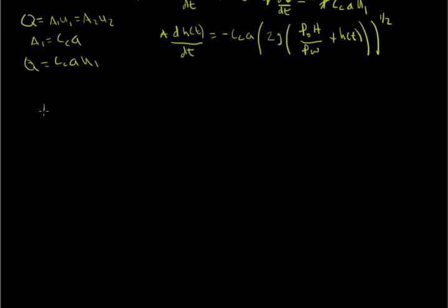So if I say that t is equal to negative A over the coefficient of contraction multiplied by the orifice cross-sectional area, and then this is going to be divided by the square root of 2g. I can pull that 2g out and just leave this inside the integral. Then I'm going to integrate that from 0 to H, integrating over the initial height.